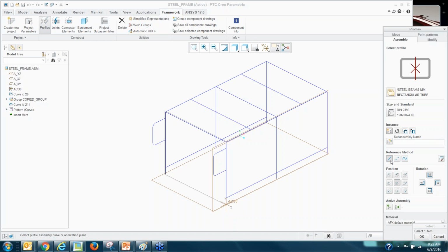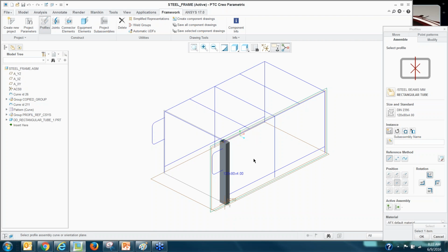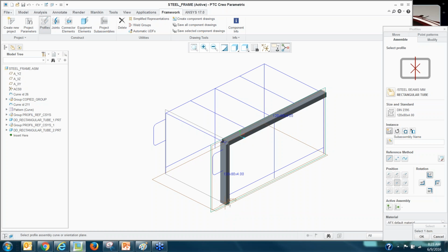And how do I place it, right? You have some placement options: curve, points, bend curve, etc. But first, I got to select my datum plane, as to how it's going to be oriented. So once I select the plane, I could select the point, or the curve, I should say, and I can select additional curves. And you see how it starts to place it, and it labels it with a 3D annotation there.